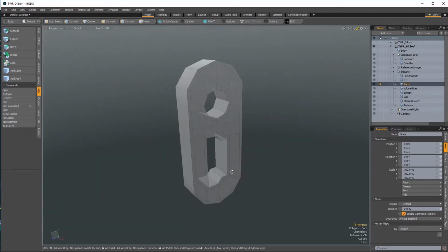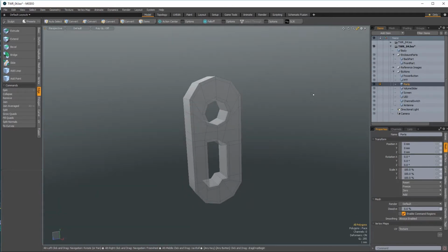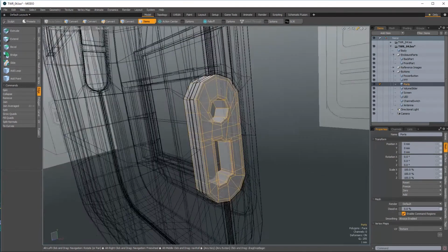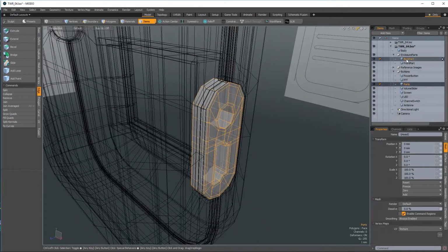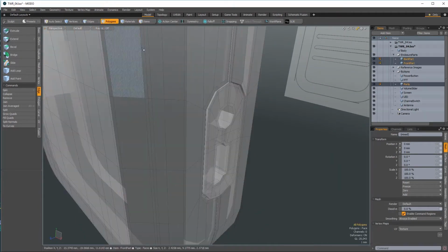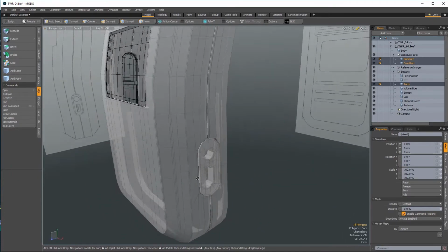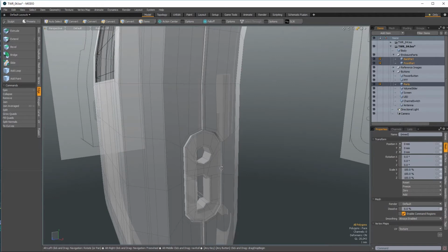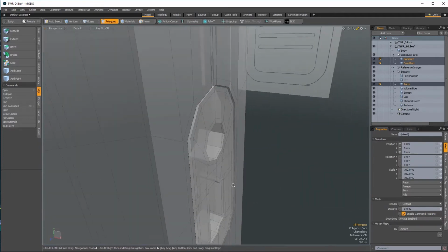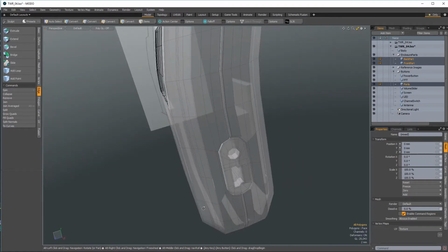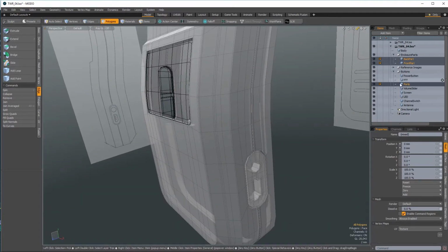There's one other problem with our shape, and that is once we look at this with the rest of the pieces, I'll just hit U to unhide them. And I'll just select the front and back face here. You can see that you could just see right through our product, and that doesn't look right at all. So we're going to put in some temporary geometry behind here to act as a blocker so that when we look at it from this angle, it's not going to look so strange and hollow.